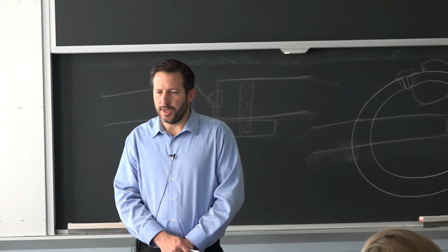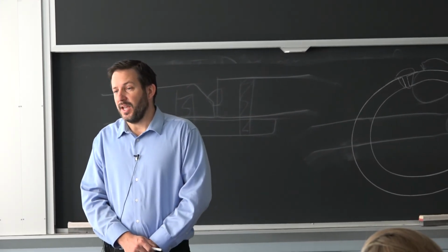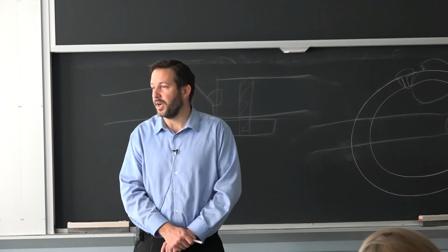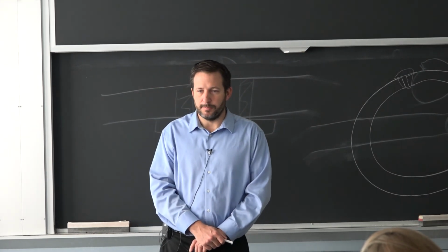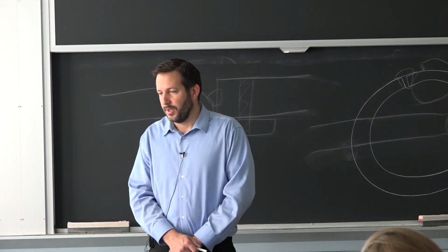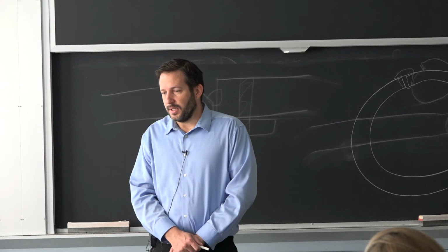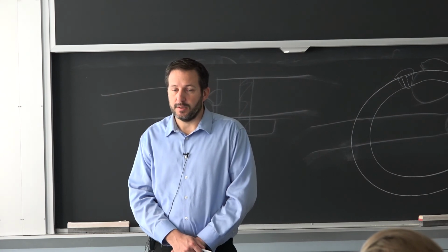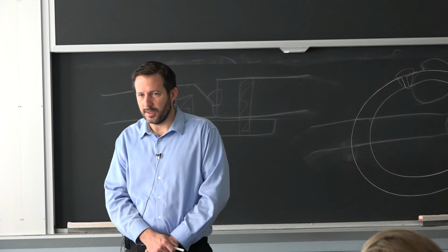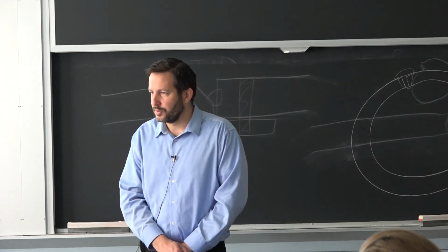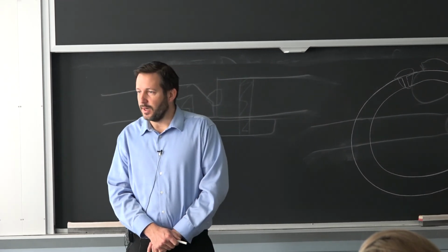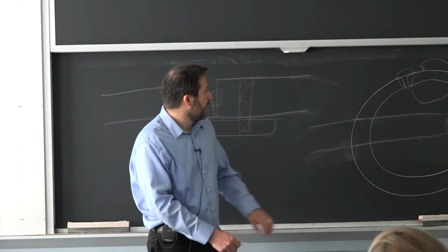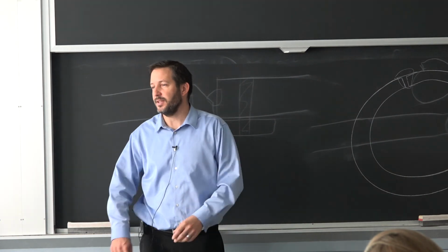And the report spoke to a number of factors. The main one being they didn't really know in details, the pipeline operator, what they had for pipe underground. And when we talk about the consequences of an event like this, it does have a beneficial effect because it did take a while, so it happened in 2010, but this year there is a pending proposed rulemaking that's going to require the operators to go and find out what exactly their assets are, how they welded, what kind of steel strength they have.